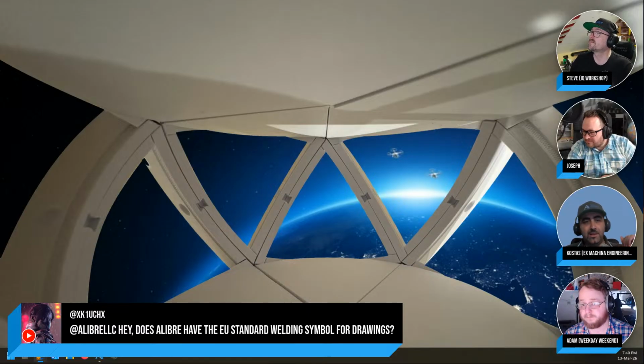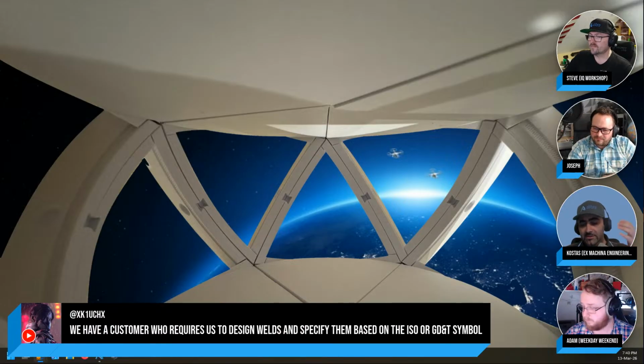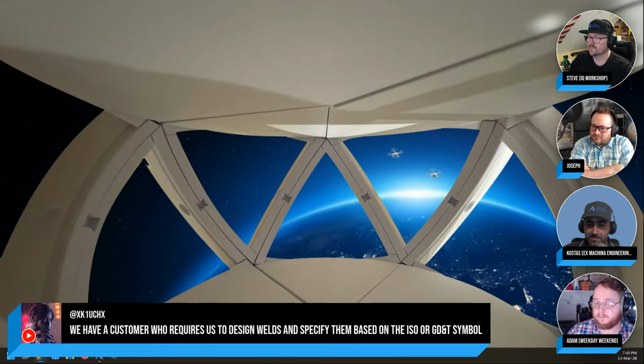For example, if you're using a 2 millimeter thick sheet, then you'll be using a bending tool that has a 1.2 millimeter radius. And you need to know that, because they might even give you K factors, and if you design differently, you might have small differences in dimensions in the final part. So, yeah, top tip there by Steve.